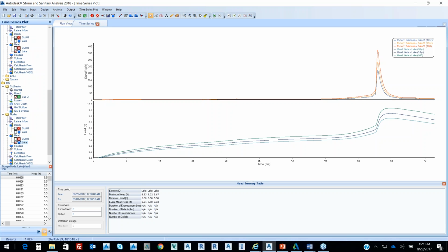So the roads for the rainfall amounts for the 24 hour for the roads was 9 inches. And clearly we're below that for the 24 hour, which is that first one. For the design 25 year storm, 11 inches. For the 72 hour, clearly we're below that. And then the 100 year is 14. So it's just some things, and all I really wanted to do is kind of simulate some of the tools that we would use just to do something residential.